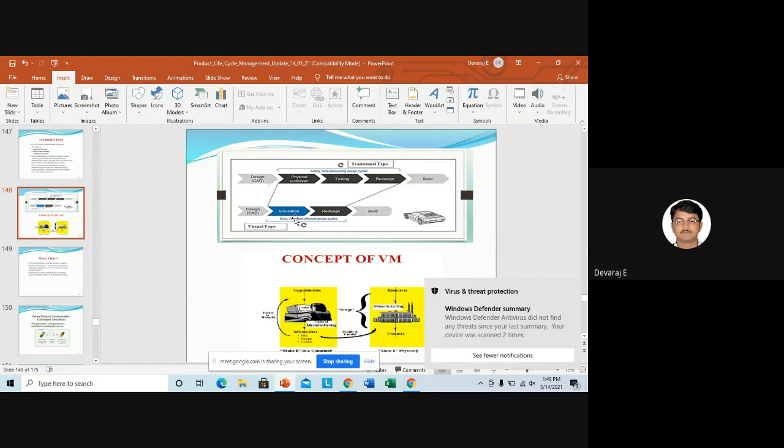If in that simulation the results are negative, or the material cannot withstand that much load or the boundary conditions, the analyst, that is your FEA head, will tell that this design is not good. Then the product design engineer takes the design and tries to remodel it, and sends the new design for simulation. If the results are okay, only then it will go for build. Now all the companies are following the second one.